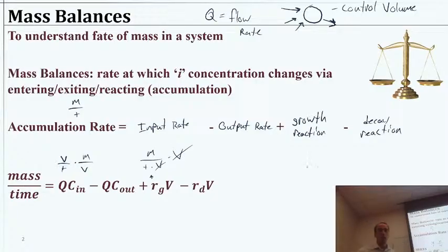So you'll see sometimes problems will have a diagram like that, and then they'll say there's an input. And you'll notice the units are mass per time input. It's still an input. It would act a lot like one of these input flow rates. It just doesn't have any flow because it's some mass over time, right? That could all work just the same as a flow rate, except we're not adding any water. So what I'm trying to paint here is the picture that it doesn't really matter exactly how we're putting inputs. It's just whenever something's crossing our control boundary, that's when we have an input.